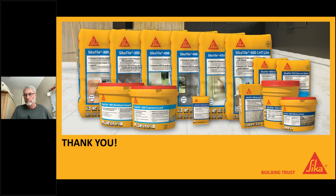And then epoxy grout for it, as long as we're following our perimeter EJ171 around the perimeter joints, I would be okay with an epoxy grout as well. So white adhesive or mortar and white grout.